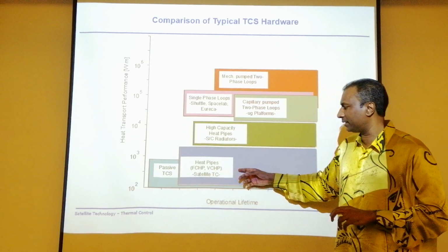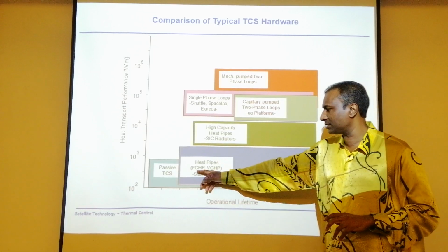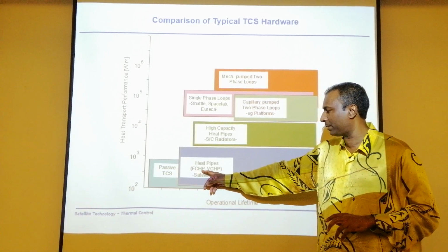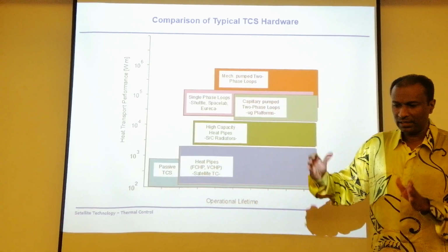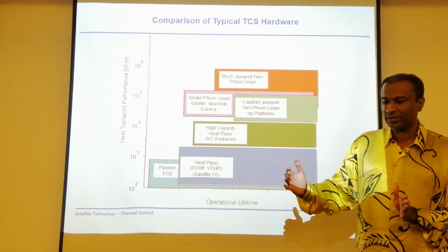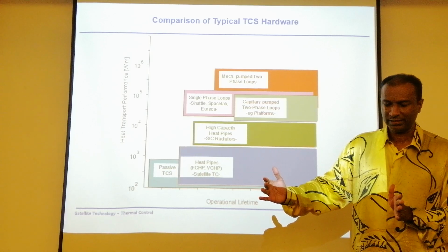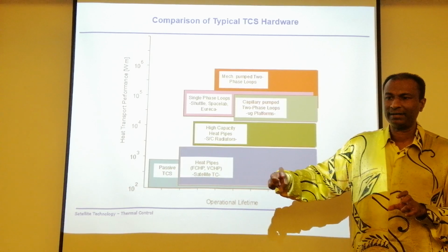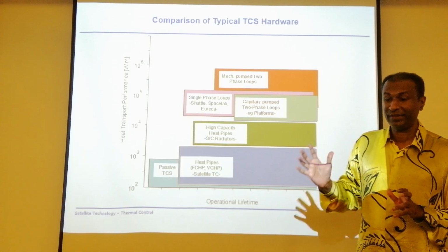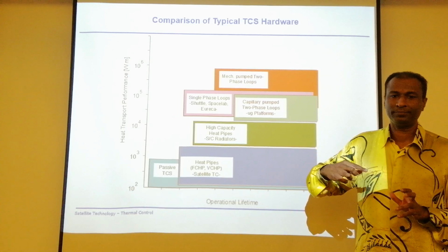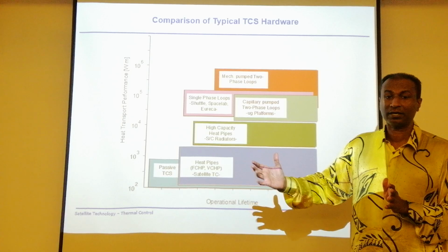Then you have types of heat pipes, basically for satellites. This is a fixed conductance heat pipe. This is a variable conductance heat pipe, meaning fixed, that means the transportation, let's say you have a particular distance, the conductance of it, that means the capacity of heat rejection, is fixed throughout the system, or you can have multiple kinds of conductance. That means the conductance can be different.